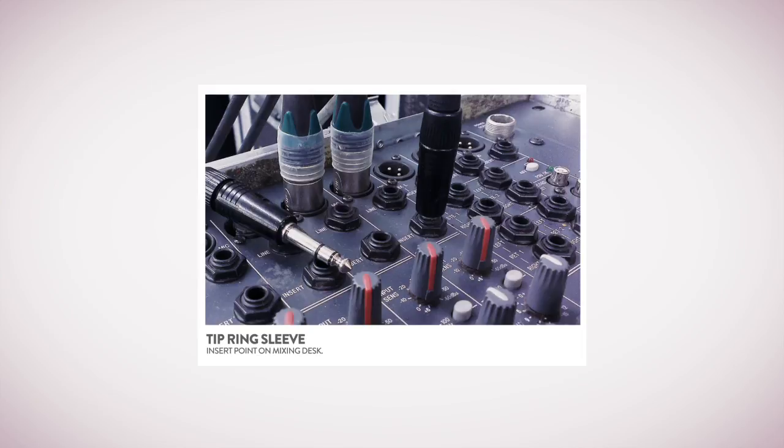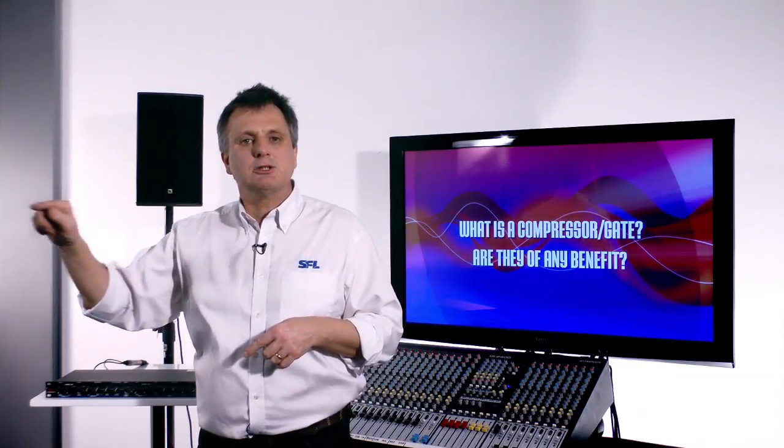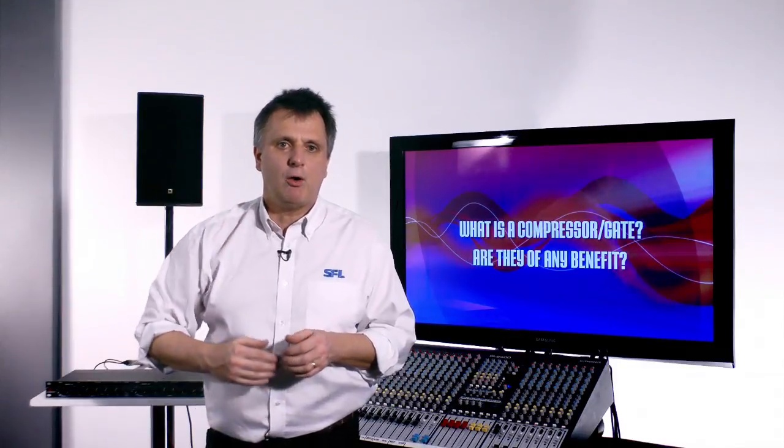We place often a jack cable with a tip, a ring and a sleeve. We leave the mixing desk, we go through the compressor, and then we come back into the mixing desk again, and then we carry on flowing down the channel through the EQ and through the auxiliaries. So the path is to the microphone preamplifier, then we take a little journey out of the mixing desk to the outboard effect, in this case a compressor, and then we return back to the mixing desk to carry on the flow as we did before. Can you therefore see that when we do compress, this pretty much affects everything downstream of that insert point?